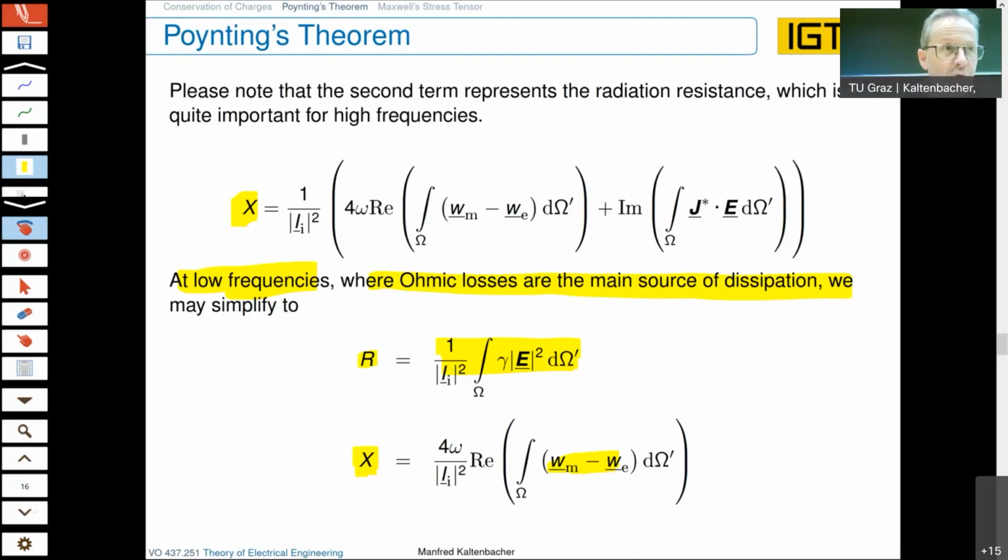That would be again what we have discussed with the simple setup of a coil and the plate, where we have seen that the imaginary part of this magnetic field is really concentrated at the plate, and that is due to the eddy currents, which are generated according to our relation coming from Faraday's law, that a time changing magnetic field generates the curl of an electric field.